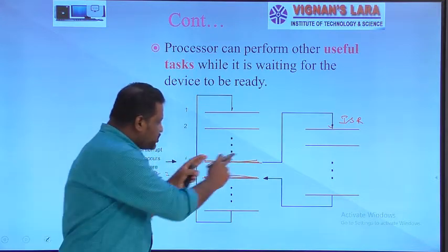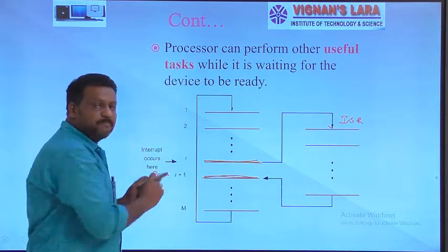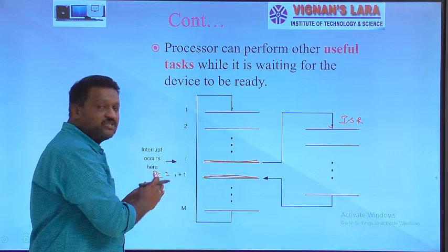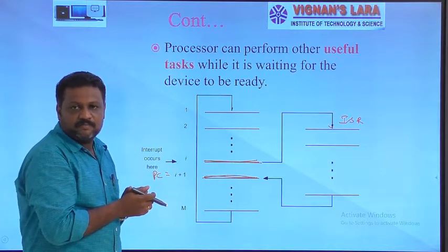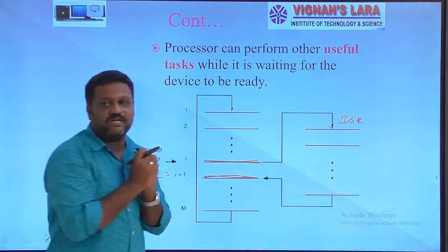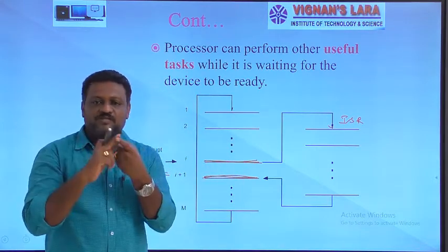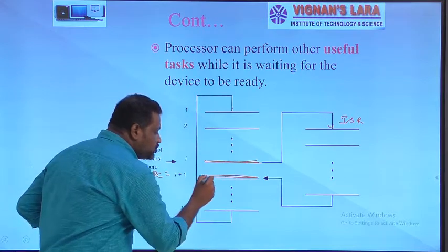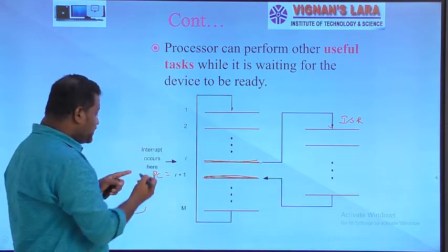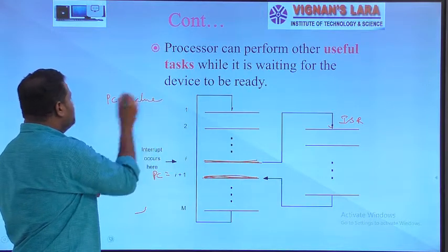Right now, the instruction I was executing in my system, at that moment the program counter PC points to the address of instruction I+1. So once our processor identifies that after execution of this instruction it received an interrupt, then first of all it stores this next instruction address, that is, the PC value, on the stack. This is the first thing it does.